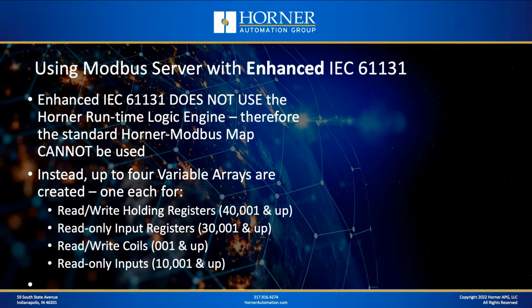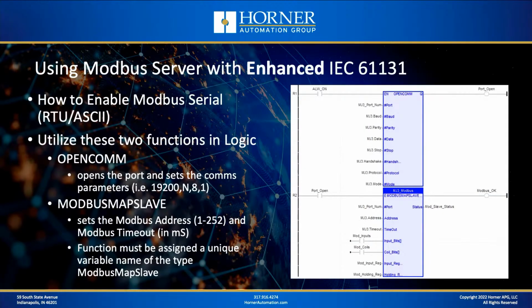Okay, so again, we can match how much data we want to share with the size of our array. Now, serially in Enhanced IEC, it's very similar. We're going to do it in logic to enable serial Modbus slave. Now, we still use the OpenCom block. That's the one we're going to use to, again, open or select our port, as well as to set all of our parameters like baud, stop bits, etc.